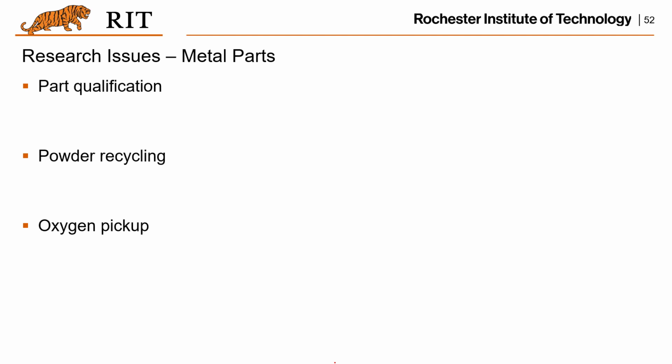Again, qualification will be a very big problem for many applications, especially aerospace, airplane, and biomedical ones. You have to make sure the built part will be as good as the one built using other manufacturing processes. And how to recycle the powder? Because the powder is so expensive, definitely you want to find a way to make the best of recycling the powders. And yeah, that's pretty much all for metal additive manufacturing.